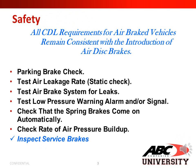Before we get started, let's go over some safety. All CDL requirements for air brake vehicles remain consistent with the induction of air disc brakes. You must perform a parking brake check, test air leakage rate, a static check, test air brake system for leaks, test low pressure warning alarm and or signal, check that the spring brakes come on automatically, check rate of air pressure buildup, and inspect your service brakes.